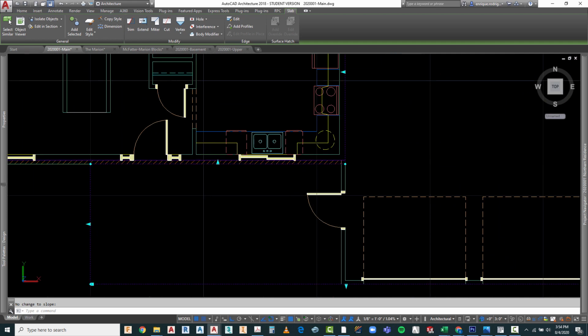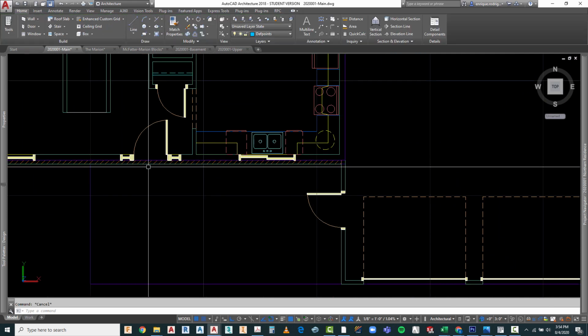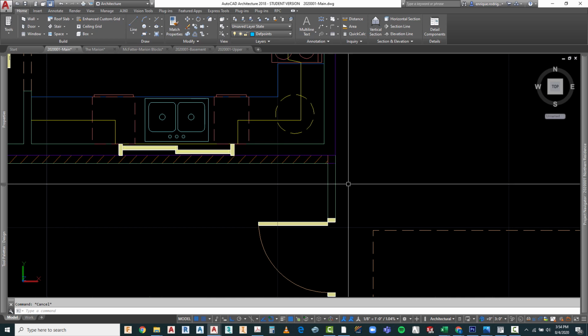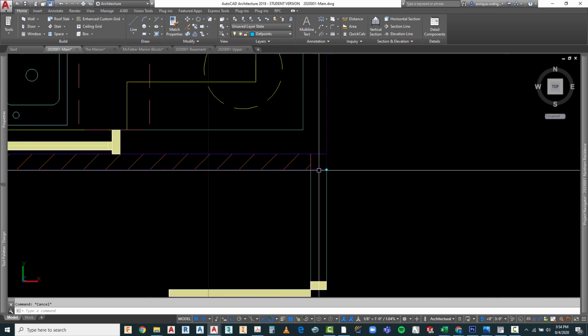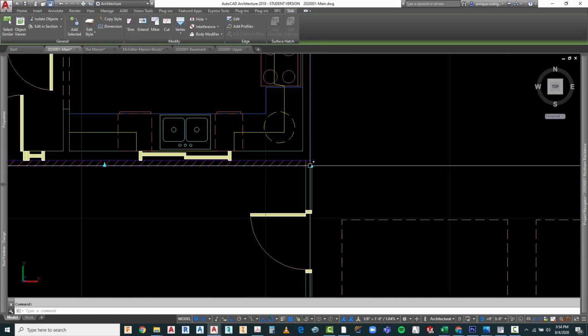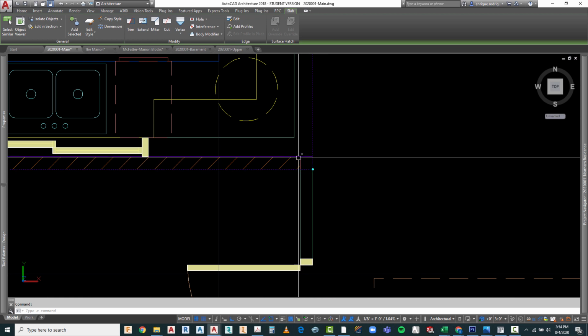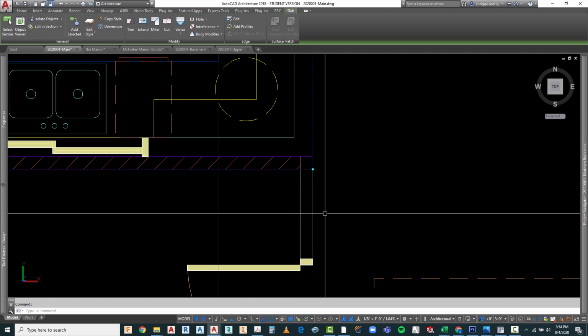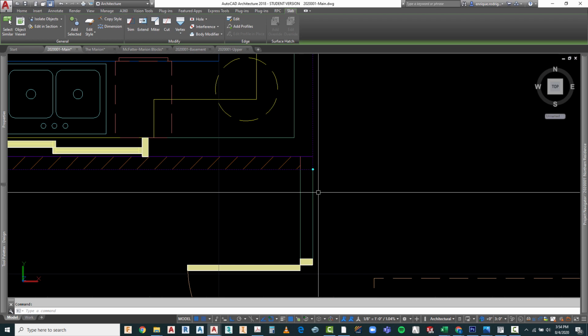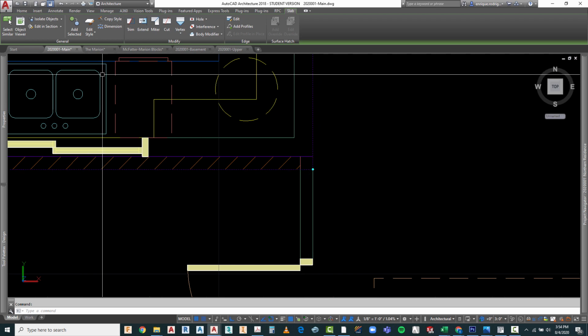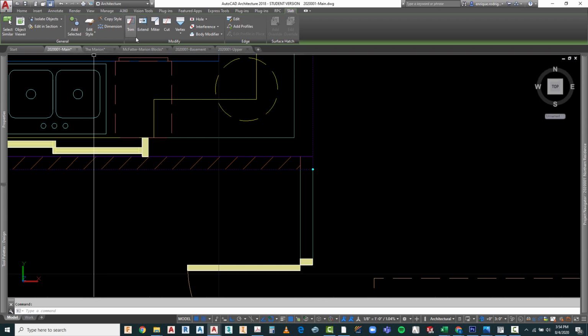Because with our wall here, we're going to carry this down all the way to the wall down below. So I've actually got a little bit of makeup that I need to do for this little corner of that slab. So how do we do that? Let's highlight that, and we can see if we can add a vertex.